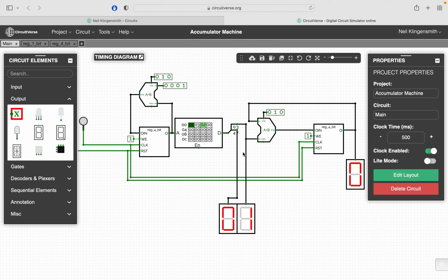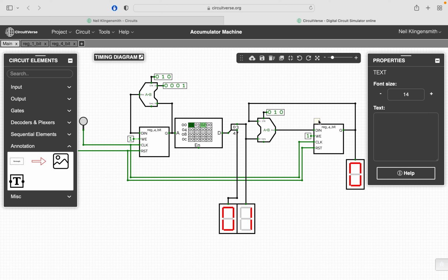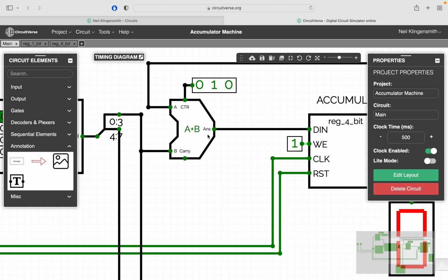Let's get started implementing this load immediate instruction. Basically, we want to take the immediate field from our opcode that's coming out of the instruction memory here, and put it directly into our accumulator. You can see our accumulator over here. The thing about the accumulator at this point is that, at least the way we have it structured right now, the only input to the accumulator can come from the adder. Right now the only instruction that this machine implements is add immediate to the accumulator.